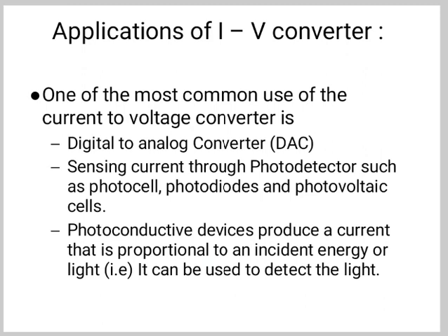So this circuit is used for measuring the light intensity using a photodiode sensor. The output of the photodiode sensor used in the circuit is current, which changes proportionally to the light intensity. Another advantage of using an op-amp is that the voltage across the photodiode remains at 0 volt.